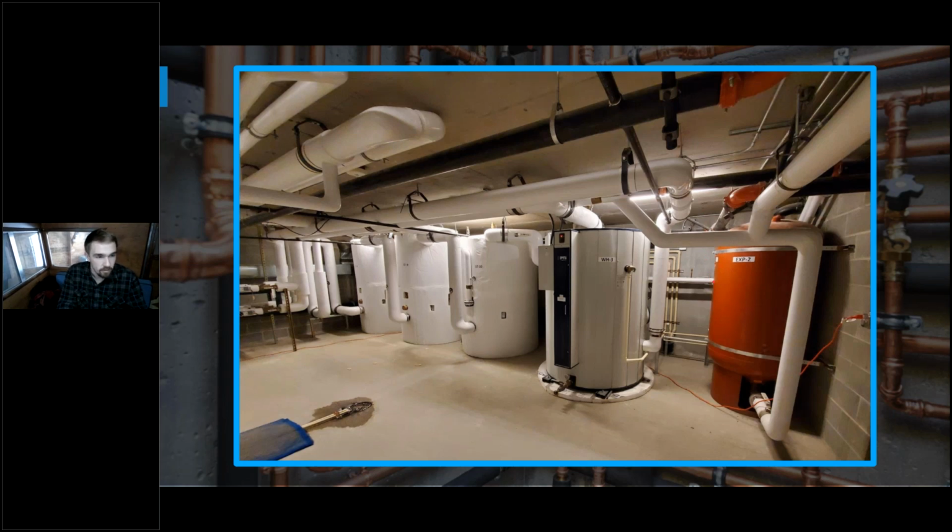Yeah, so tying that in-series storage concept to a real application, here is the storage at Jackson that we took a peek at with our first case study. You can see these 3 marshmallows here are the insulated primary storage tanks, and the top of this first tank is connected to the bottom of this next tank, and so on. And the top of this tank is supplying hot water to the building.